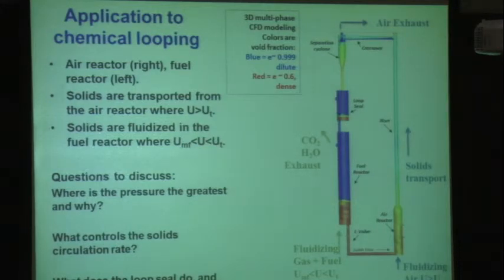So right there, right? Because all those solids are sitting above it, right? It's right at that corner. That's the highest point. And so your design is really constrained by here, and what you have to do then is carry this up high enough to create a big enough bed of solids to control the circulation rate around that process. And the way you do that, control that circ rate, is by designing to let the solids go at a controlled rate along this leg.